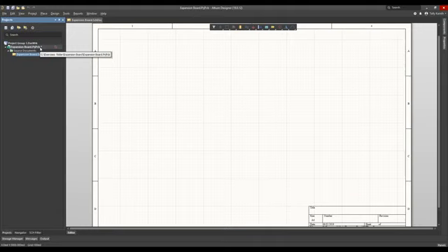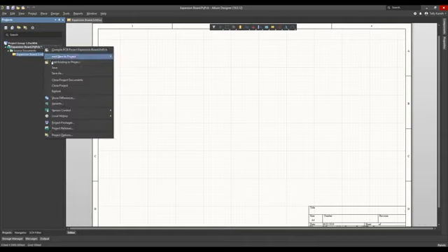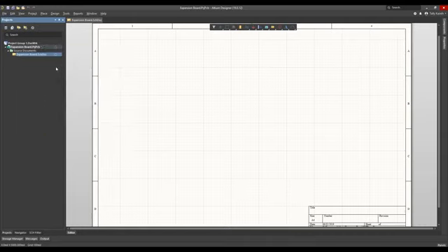The project file contains a list of all the project-related documents and needs to be saved to add the new schematics information to its list of project files. Right-click on the project file and select Save. Now the schematic has an entry in the project file and the asterisk is gone. In Altium Designer, whenever there is a change to a document, you will see the Open Document page icon turn red and an asterisk symbol indicating that the current open version of the document has not yet been saved.